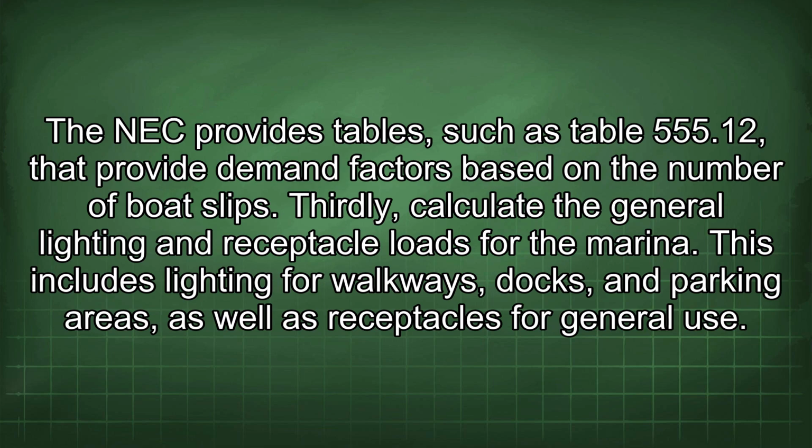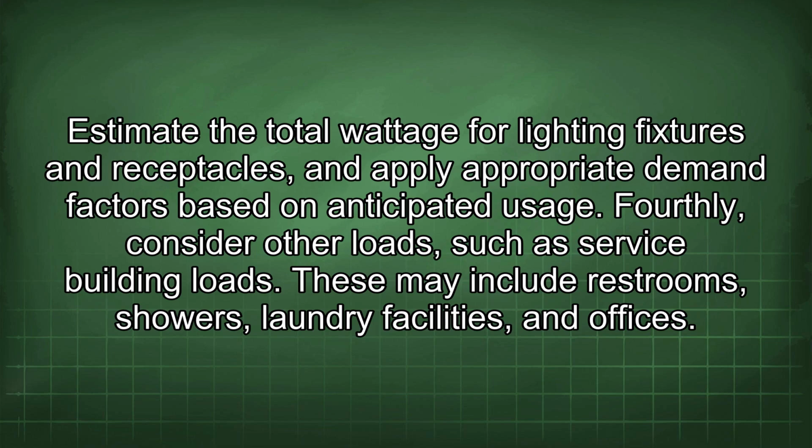Thirdly, calculate the general lighting and receptacle loads for the marina. This includes lighting for walkways, docks, and parking areas, as well as receptacles for general use. Estimate the total wattage for lighting fixtures and receptacles, and apply appropriate demand factors based on anticipated usage.